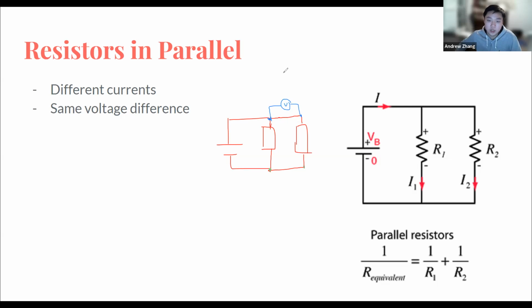It would just be 0 because, as we know, wires have 0 resistance. So Ohm's law tells us the voltage difference between these 2 points is 0. So this entire piece here might as well be the same. And for that matter, we can say this entire branch all the way around here all has the same voltage.